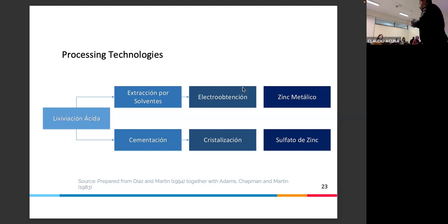You need it to explore if it's feasible to dissolve the product, and you do it with 2% to avoid any mass transfer problem, to avoid any mixing problem. This is TRL 2. Let's say in a small beaker, 2% solid, 3% solid, very small scale.